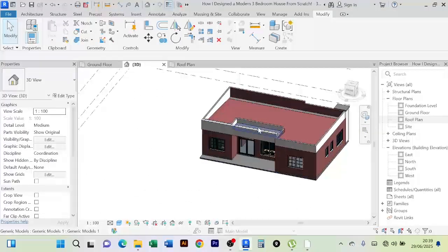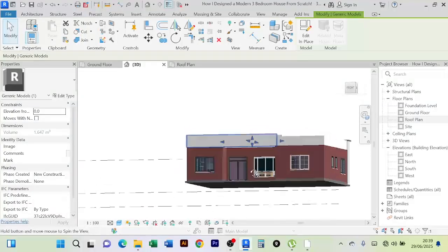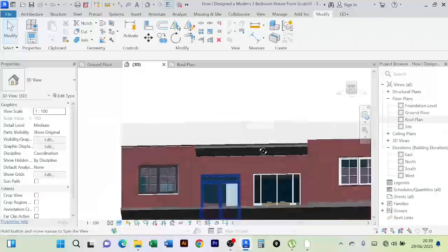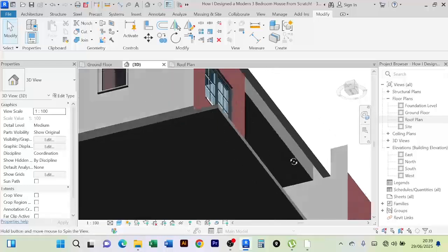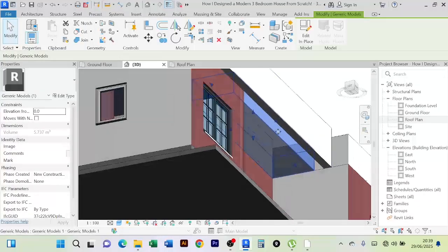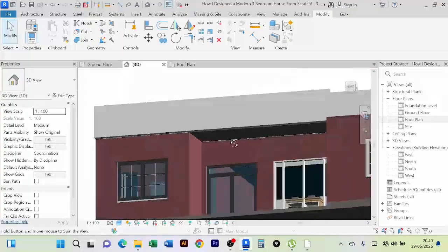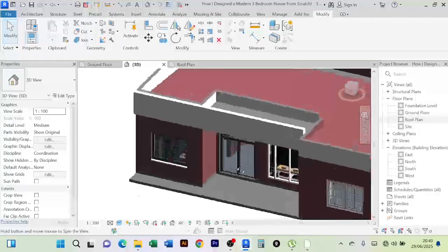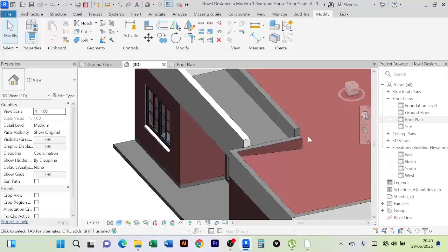And then this extrusion, this one here, I'm going to align it with this by just dragging this a little bit down like that, so that when we see from here, you see it is aligning with this, but we want this face to also align with this one. So I'll drag this one towards outside. Now it has covered that area perfectly. So that's how you can achieve things with extrusion. Extrusion is one tool that is very, very powerful when you're modeling.